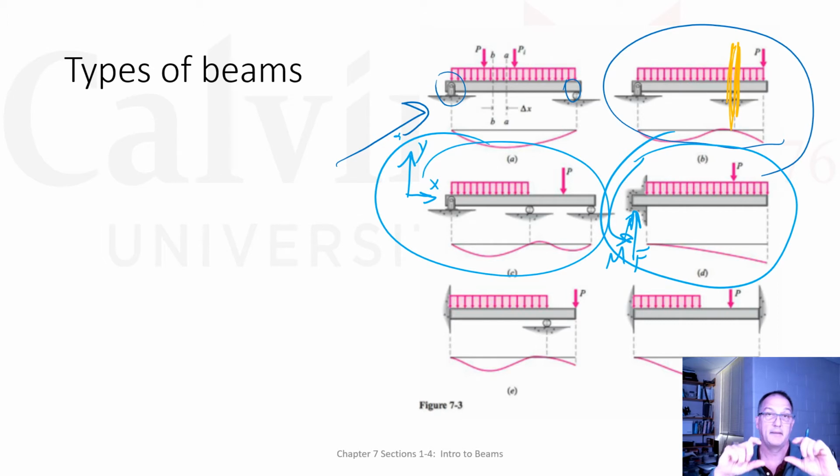Now, again, I have 2 equations: the sum of the forces is equal to 0, and the sum of the moments is equal to 0. That left end of the beam is doing both things. It's giving me a force and a moment, so I can completely define my situation. That is a static situation. I can then start doing other things.